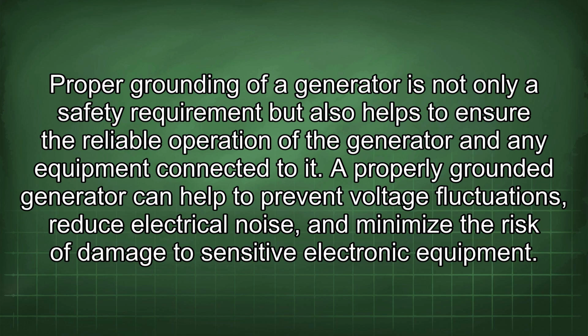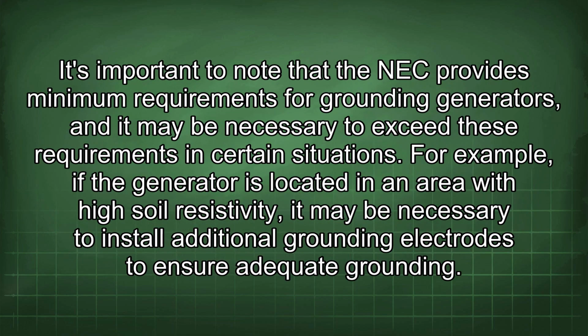A properly grounded generator can help to prevent voltage fluctuations, reduce electrical noise, and minimize the risk of damage to sensitive electronic equipment. It's important to note that the NEC provides minimum requirements for grounding generators, and it may be necessary to exceed these requirements in certain situations. For example, if the generator is located in an area with high soil resistivity, it may be necessary to install additional grounding electrodes to ensure adequate grounding.